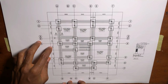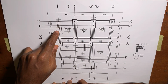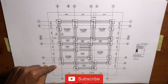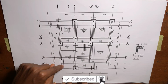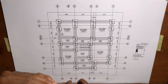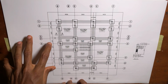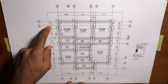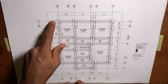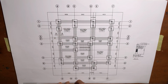If you look at this, you can see that the dimensions of the foundation were not really given here, but with these dimensions that we have at the side, we can use them to determine what the length and the width of the foundation will be. However, they've already given us a detailed drawing for each of the different types of column base in this drawing. Now if you look closely, you can see that there is a writing on each column base. We have BT2, BT3. BT means base type.